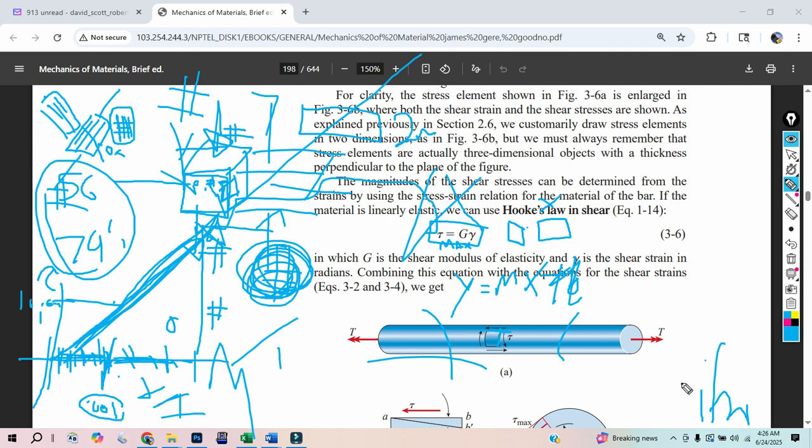But if I just extrapolated this, went over to 1, I would be at 10 million psi. But that's the slope. That's kind of mentally how I see that slope, because I think it's a little bit hard to ask what the slope is here. Well, it's just rise over run. That's 10,000 divided by 0.001. Dividing by a very small number gives you a bigger number. So that's where we get that 10 million. And so that's kind of the introduction to at least shear.